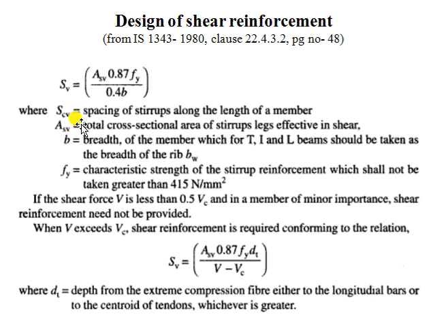If the shear force V is less than 0.5 Vc and the member is of minor importance, shear reinforcement need not be provided. So there is a condition for the provision of shear reinforcement. If shear force is less than 0.5 Vc, then there is no necessity of providing shear reinforcement if the members are of minor importance. When V exceeds Vc, shear reinforcement is required, and it should conform to the relation